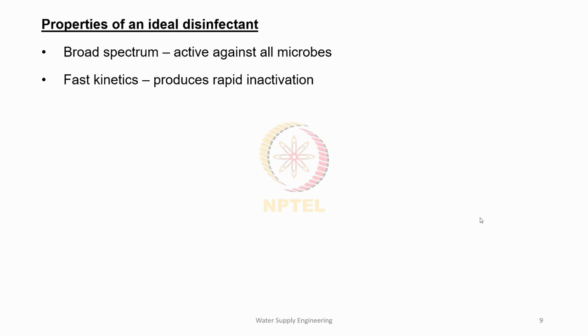Then it should have fast kinetics. That is, it should produce rapid inactivation. The reaction should be faster. Once we apply the disinfectant, it should, at the earliest, inactivate or kill the pathogenic microorganisms. The third property is, it should be non-toxic, non-flammable, non-explosive. Once we add this disinfectant to water, it should not inject any toxic nature to the water. Also, it should be non-flammable and non-explosive, so that it can be used carefree.